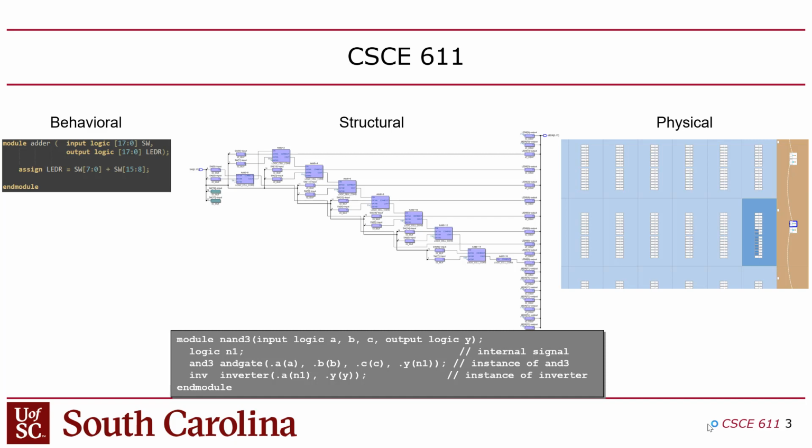Or you could design your SystemVerilog at a lower level where you explicitly instance gates in the SystemVerilog and connect them with wires. In SystemVerilog, wires are not wires, they're names. They're variable names. Okay, so kind of like SPICE. If you guys remember SPICE from when you took electrical engineering 221, wires were formed by common names of connections. And the wires were inferred by the SPICE net list. Very similar thing in SystemVerilog.